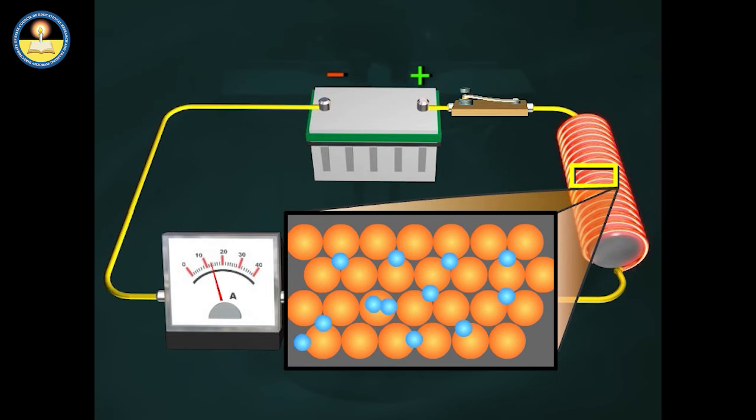Rated value of an electric fuse indicates the maximum current it can sustain. For example, an electric iron, when operated at 220 volt, a current of 4.54 ampere flows through it. In this case, a fuse rated as 5 ampere is used.